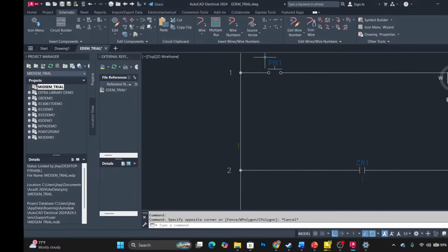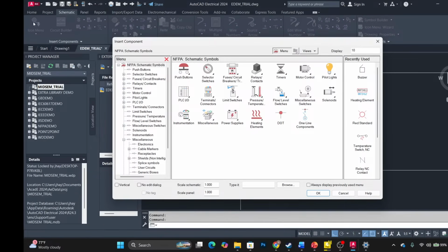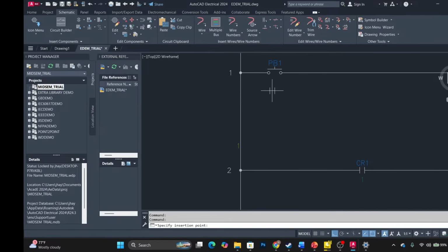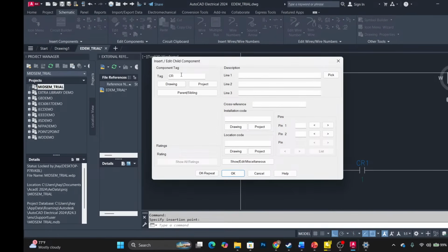The instruction is still in rank one, and you're connecting it parallel to this. Now you can go and put it on rank two. So watch what we are going to do. Go and select the contact. Let's take the normally open contact, and let's label it CR5.